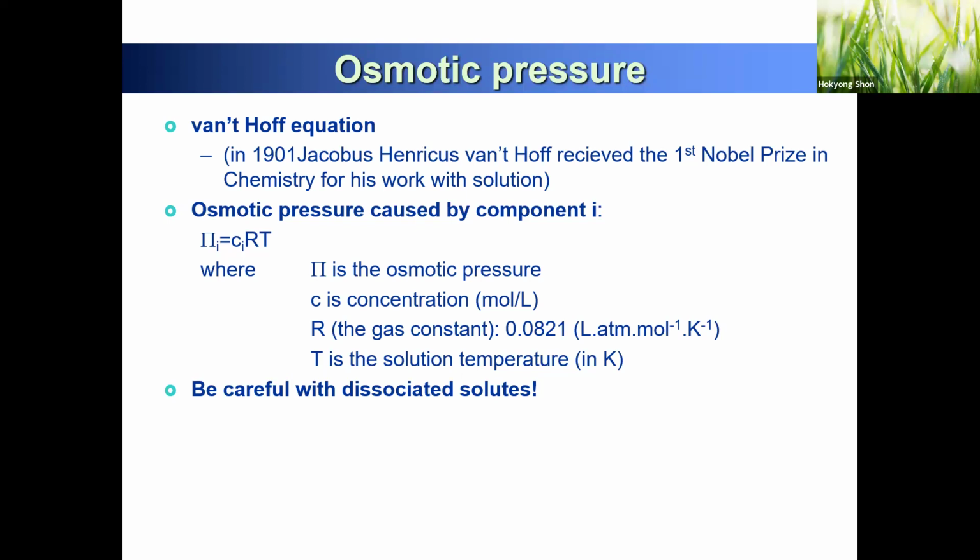It means like 50 grams per liter, let's say double, because you have 50% water recovery in seawater desalination. So the 35 grams per liter brine will be 2 times because of 50% recovery, which means 70 grams per liter of brine will be produced. With 70 grams per liter, your seawater osmotic pressure will be double, which means 27 multiplied by 2, so 54 bar for the brine.